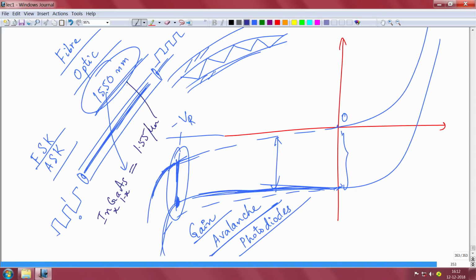This is the same thing as this, right? This is an InGaAs photodetector. An InGaAs PIN diode can be used, which is just like a PN junction except that there is an I layer in between. I'll come to that very soon. InGaAs PIN diodes are commercially available at these wavelengths, and even other wavelengths you can buy. So this is your photovoltaic junction that you are using for detecting the wavelength.